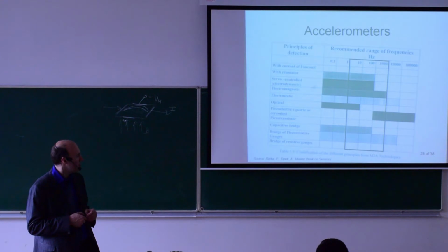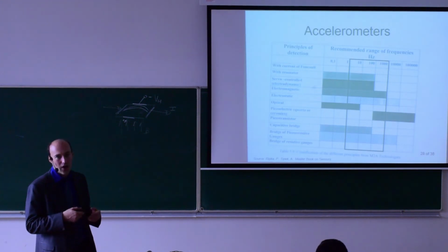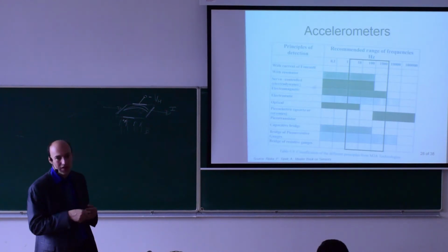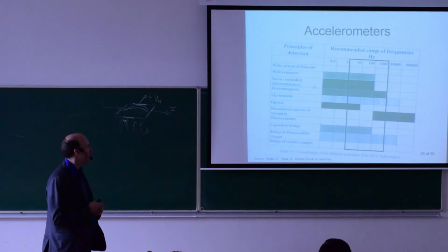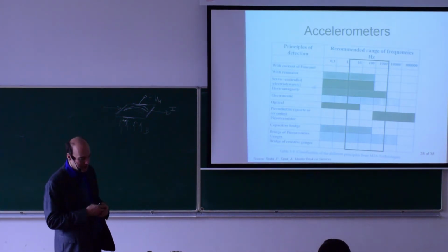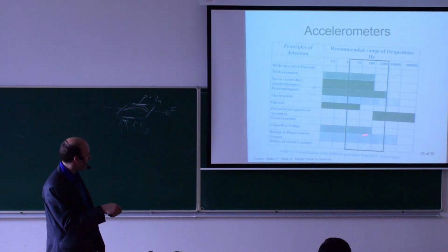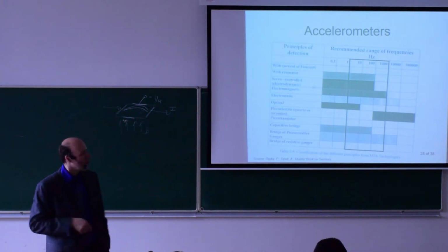If you want to use it as a vibration sensor for high frequencies, then you have to use a piezoelectric sensor, which on the other hand is not working for low frequencies. So again, by application, you need to select the correct sensor principle. We will discuss only this capacitive bridge sensor.